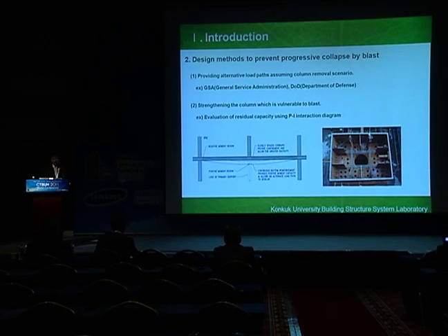Because determining the failure of a column after blast is very difficult, he just assumes the column is removed, and then investigates the alternative load path.